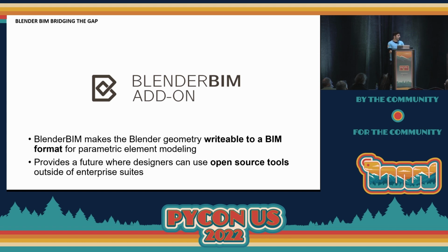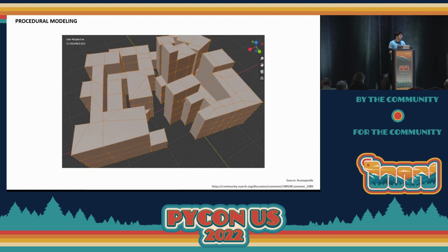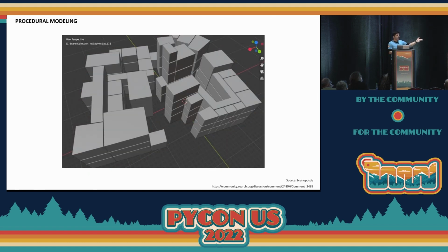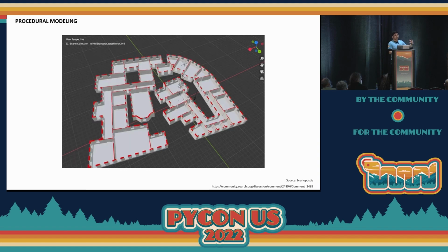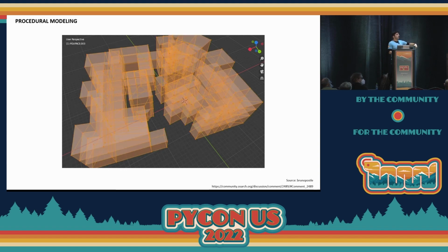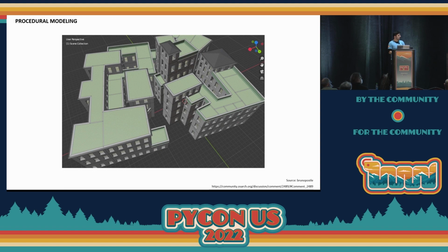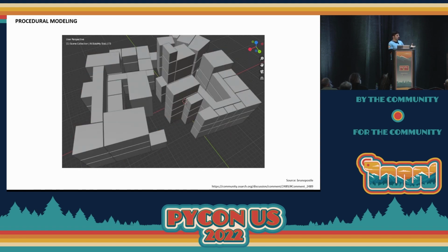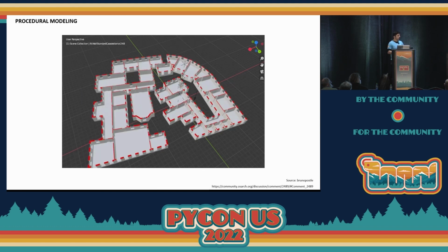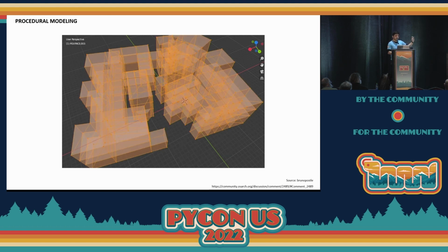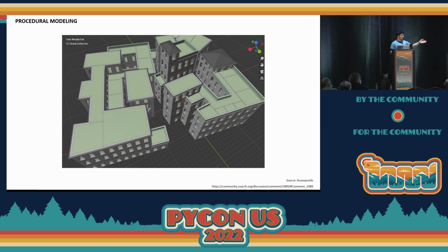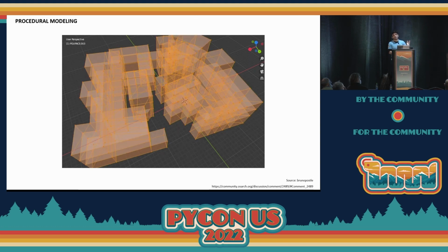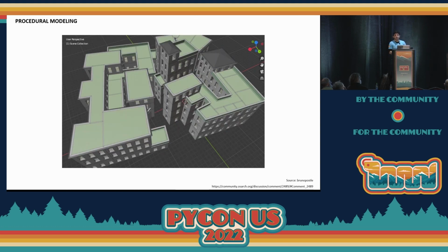So this is the middleman here that can quickly take your model ideas into a software where you can continue working on the database side. And that's what happens when you have the geometry and meshes from the Blender solution and scale it up for a building. All you're doing here is just taking those meshes, making those shapes. The shapes then have solids. The solids then become loaded with walls and doors, architectural elements. And then you can at the end see that section of a floor plan that you can then put on a sheet. Very, very fast, very cool.